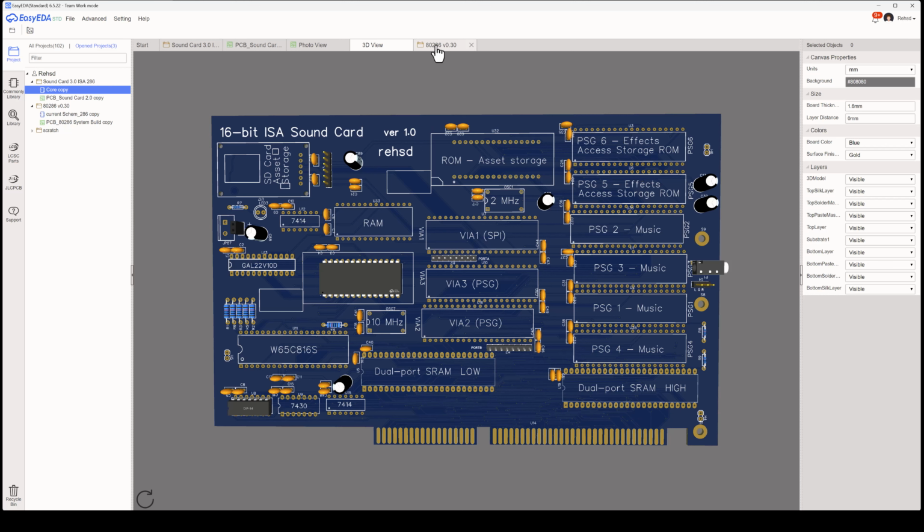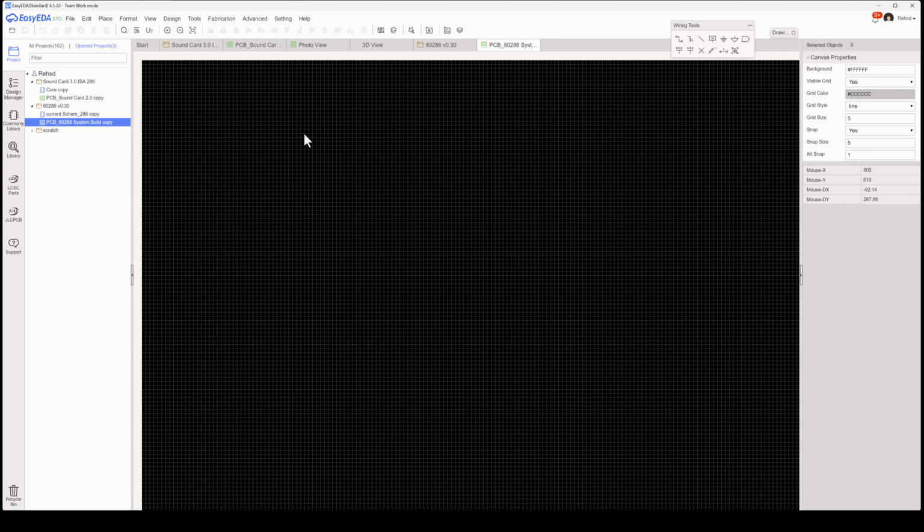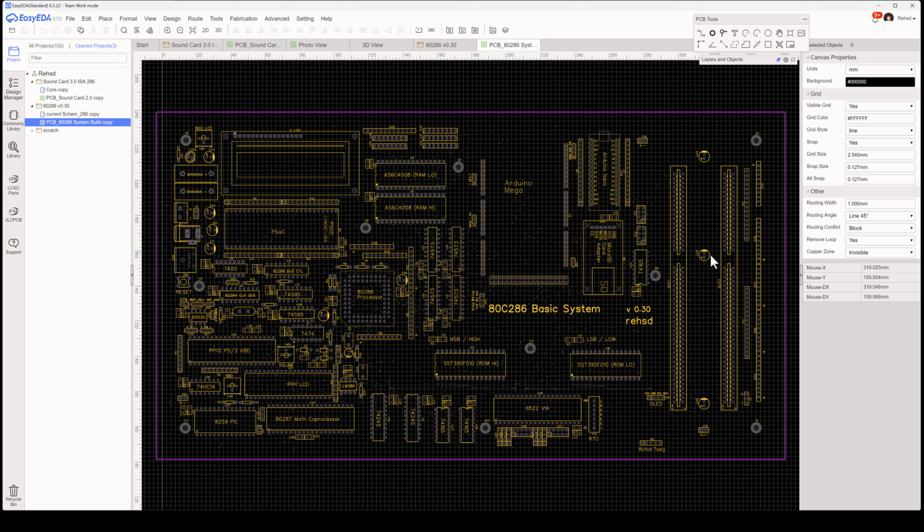And on my ISA slot, if I go back to that for a second and look at it, this is on my system board, the 286. If I take a look at that, I do have capacitors spread here too. So when these cards are plugged in, they're pretty close to these capacitors here. And I can go with a pretty large capacitor there if I want a bulk type capacitor. And as I add ISA slots to this board, I'll put in more of those capacitors, just to follow the ISA slots.